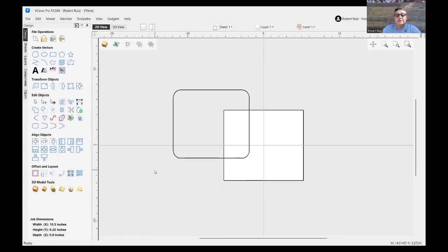And you can go ahead and close that. You can see that it created a rectangular box, pretty much the size of the material that you have. So what we need to do is we need to get this in the center of our material. All right, so here's the second tool you're going to learn, which is how to center your objects.